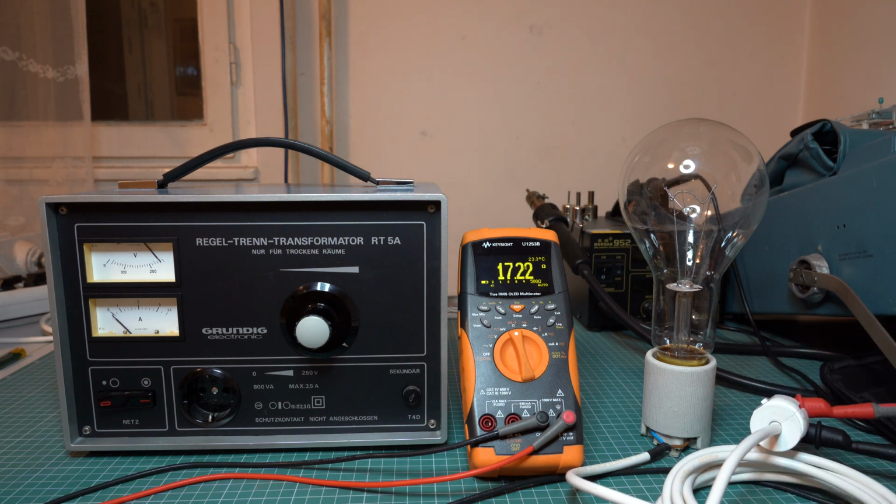And as you can see, the value is a lot different. It started at around 20 ohms and it keeps going down. And the fact that it goes down is also a clue about what I'm trying to say here. So the explanation for all this is the positive thermal coefficient of the filament. The filament is probably made out of tungsten, and like most metals, tungsten has a positive thermal coefficient, which means that as the temperature goes up, its resistivity goes up as well.